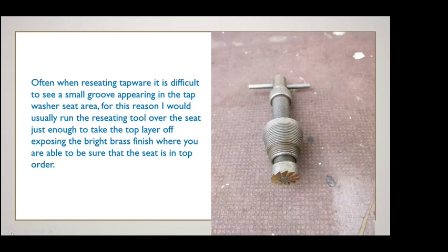And you just want to adjust it so it's just touching, by screwing the main section down, this bit here. So you screw that into the tap with it loose, then you wind that down till it just touches it, and then you spin this around by holding it so it doesn't over tighten, and just skim it very gradually. You don't want to go grind. You just want to skim it, take it out, check it, flush the stuff out, make sure it's all nice and gold shiny looking. If there's a black line through it, keep going till you get it all nice and smooth.